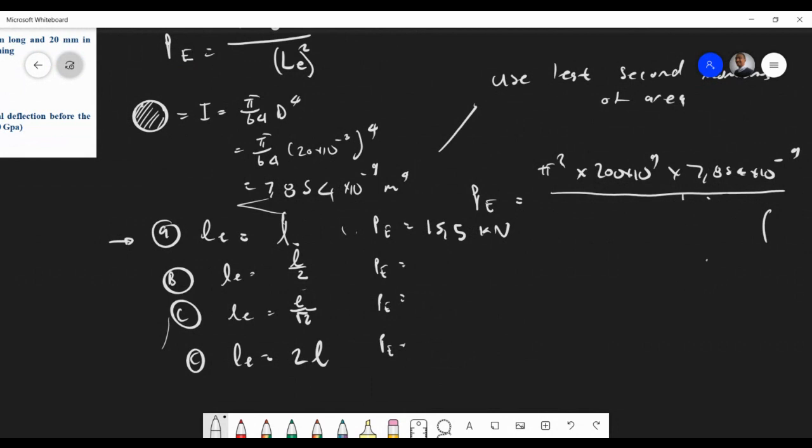So both ends fixed will be 4 times 15.5, which will be 62.012. Okay. So again, we can already see that, depending on the condition, when it's fixed there is a higher critical load. This is the idea they're trying to show, for this particular section obviously, but it'll follow suit similarly.